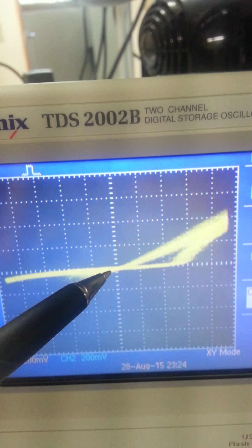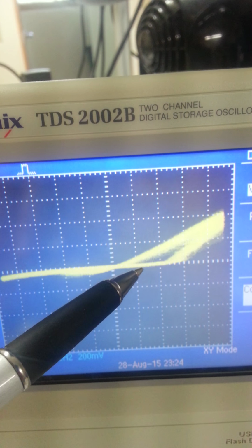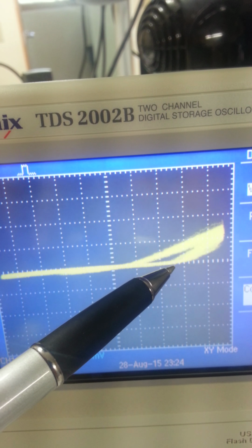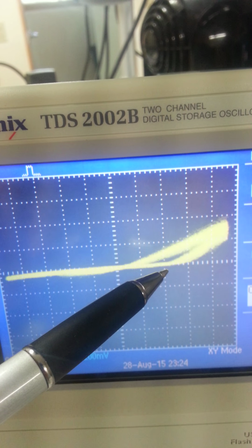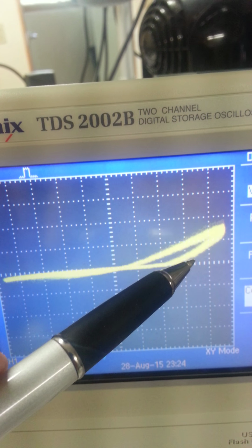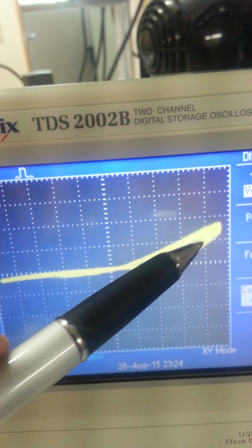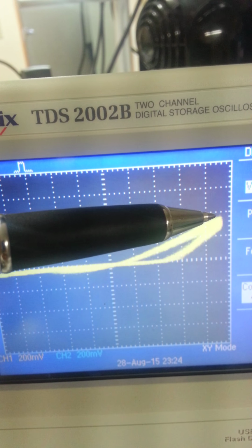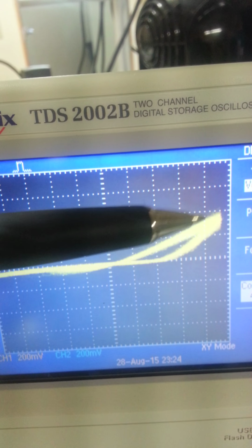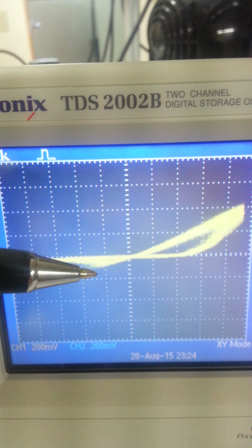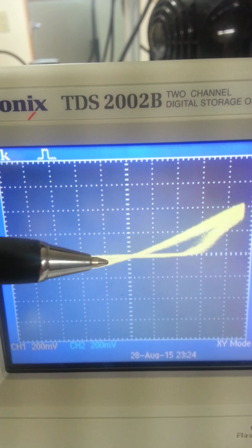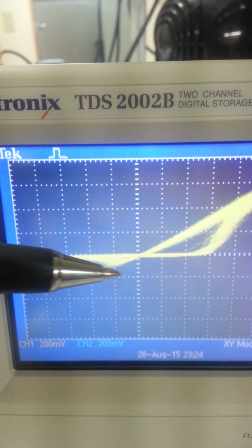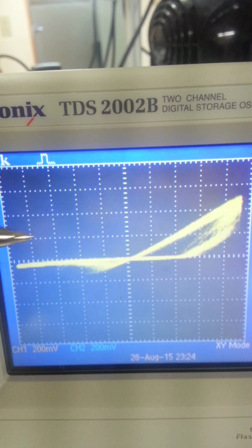Now, as you can see, we start off on the sweep in the low conductance or high resistance state. We hit the forward adaptation threshold, and we start to increase the conductance of the memristor, decrease its resistance, until we hit the low resistance state. Then we sweep down until we get to the reverse adaptation threshold, and that'll take it from the high conductance state back to the low conductance state, and the cycle repeats.